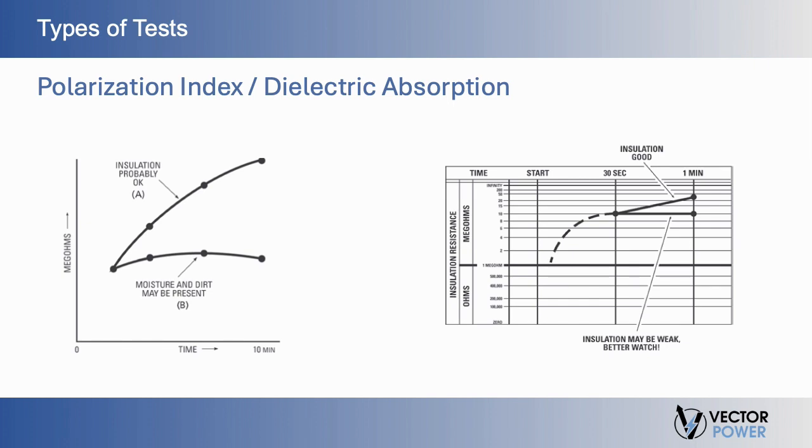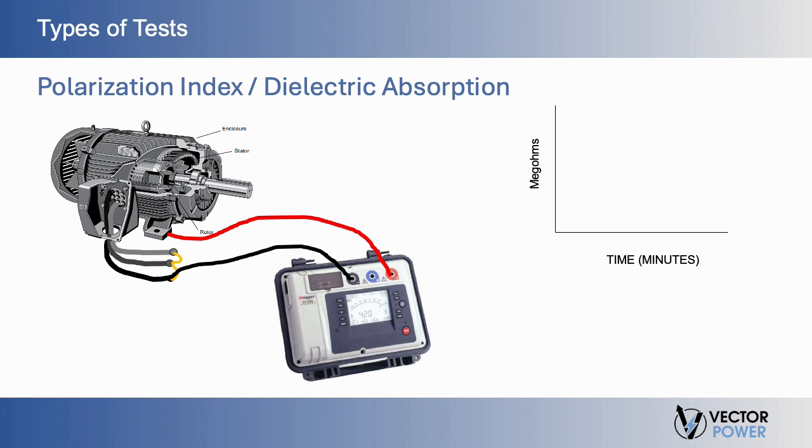Resistance readings alone are difficult to work with, as they may range from enormous values in new equipment down to a few megohms just before removal from service. A test like the PI is instrumental because it can be performed on even the most extended cables, yielding a self-contained evaluation based on relative readings rather than absolute values. The polarization index test is a famous test that is performed on rotating machinery. It is called out in various testing standards.